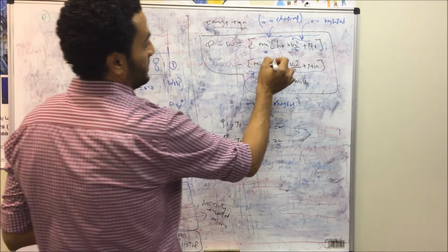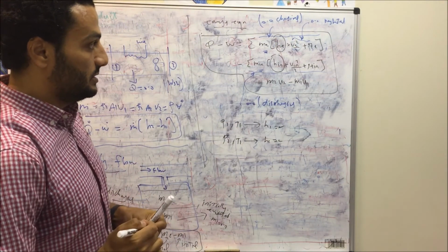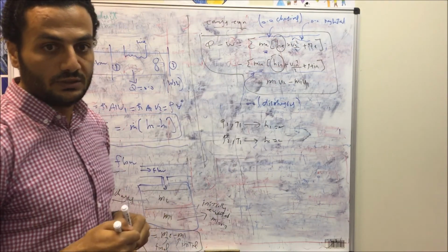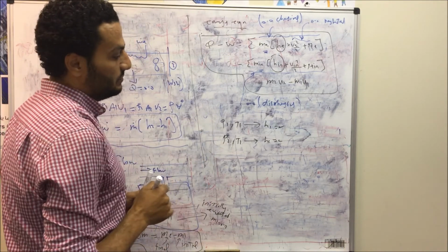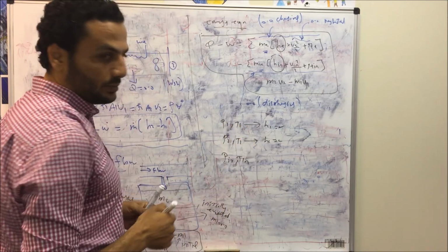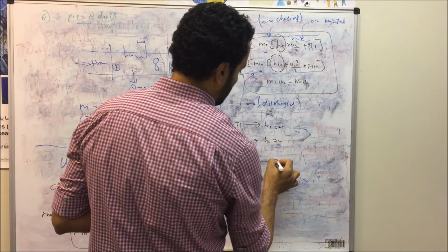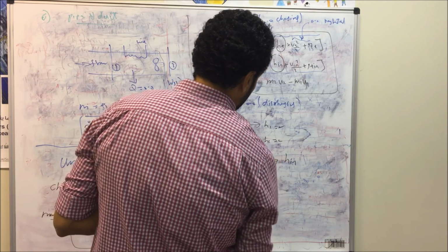What about H exit and H inlet? In case of discharging we need to calculate H exit, in case of charging we need to calculate H inlet. If the working fluid is steam, the conditions will be given, P inlet, T inlet, or any other two properties, so we can calculate H inlet using the tables.